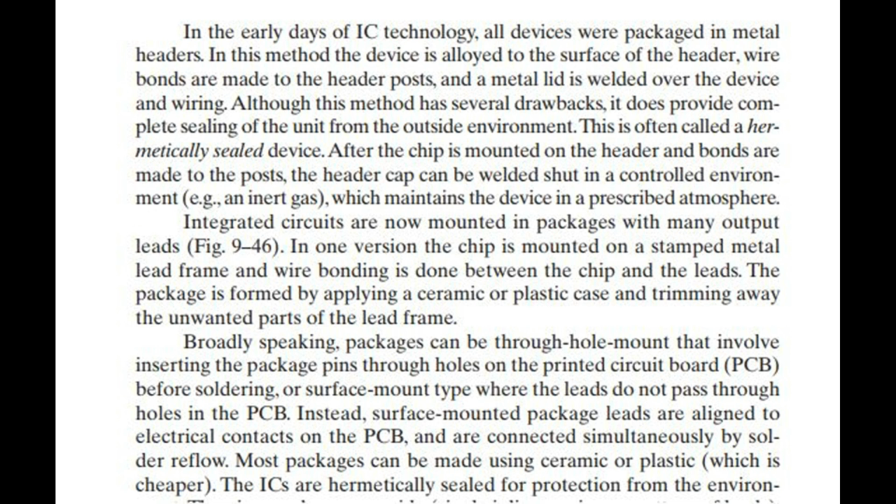Broadly speaking, packages can be through-hole mount, which involves inserting the package pins through holes in the printed circuit board, PCB, before soldering, or surface mount type, where the leads do not pass through holes in the PCB. Instead, surface-mounted package leads are aligned to electrical contacts on the PCB, and are connected simultaneously by solder reflow.